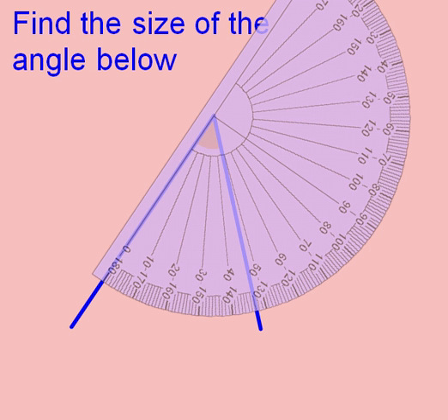I can now put my protractor back on. The baseline is lined up here. I can see that I want to use this 0 on the inside scale. I can count around to 40 degrees. I then need to look carefully here and see that it's 41, 42, 43, 44, 45, 46, 47 degrees in total.